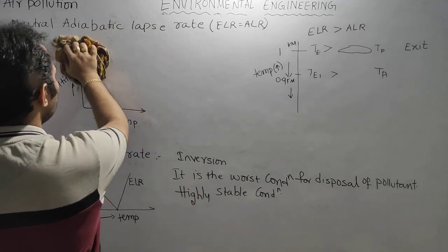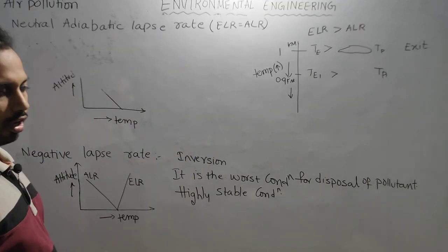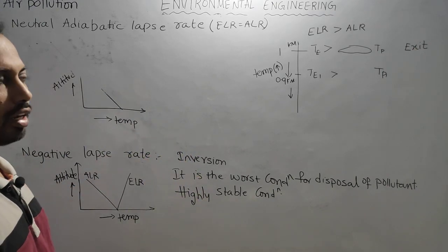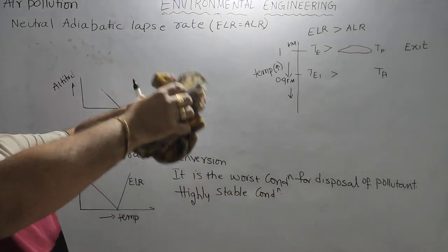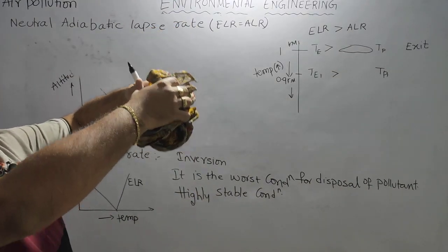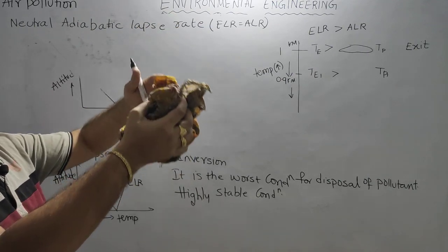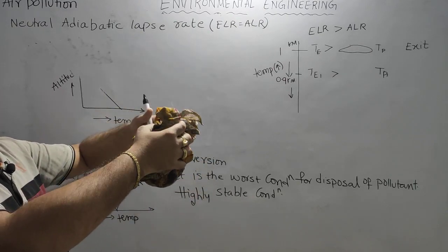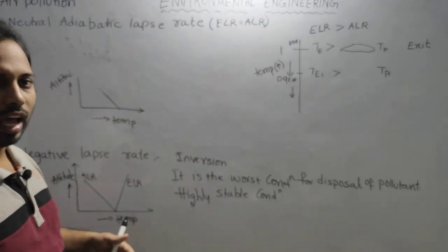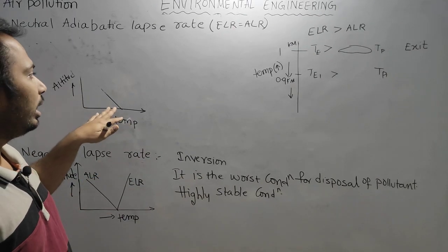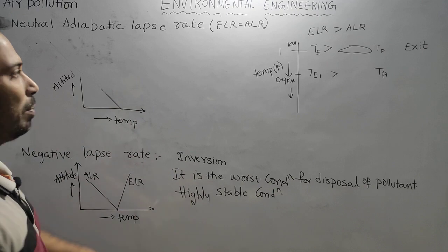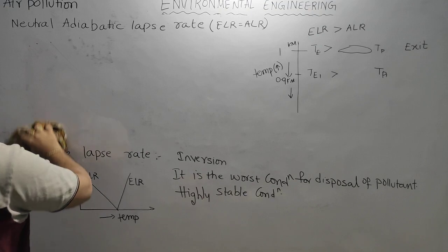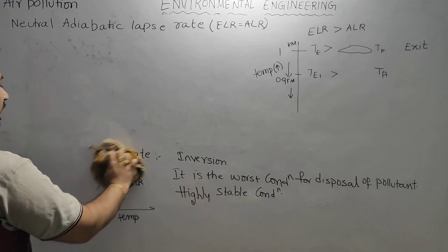Depending on that, we have what we call plume rise models. Plume is nothing but the smoke coming out of the stack. The plume rise model describes how it rises out of the stack and how it moves in the environment, depending on the environmental lapse rate and also wind flow and pressure outside, because many factors affect these plume rise models.